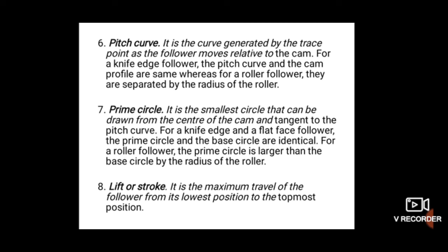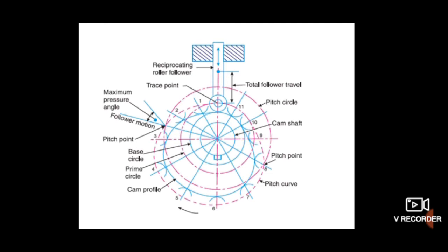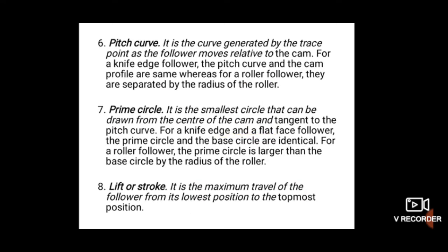Next and last terminology is lift or stroke. It is the maximum travel of the follower from its lowest position to the topmost position. So if we rotate this cam, the follower will move vertically. So from the lowest position to the topmost position, this distance traveled by the follower is known as lift or stroke of the follower. Stroke of the follower is a very important terminology while designing the cam profile, because while drawing the cam profile we need to draw a displacement diagram, and for drawing the displacement diagram we require the stroke of the follower.